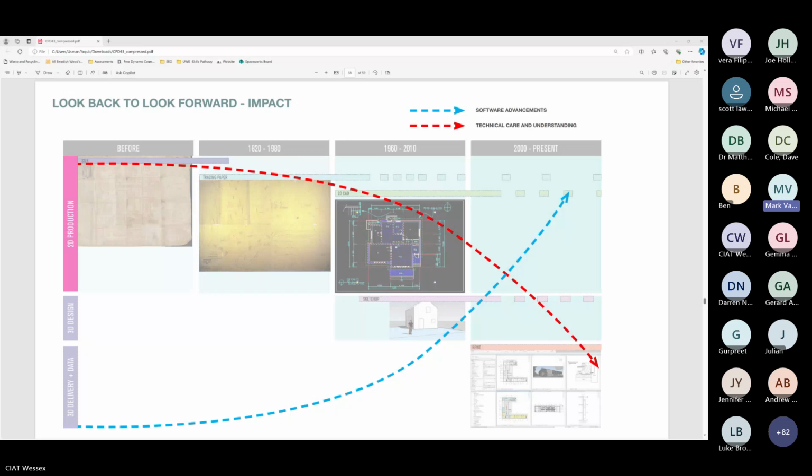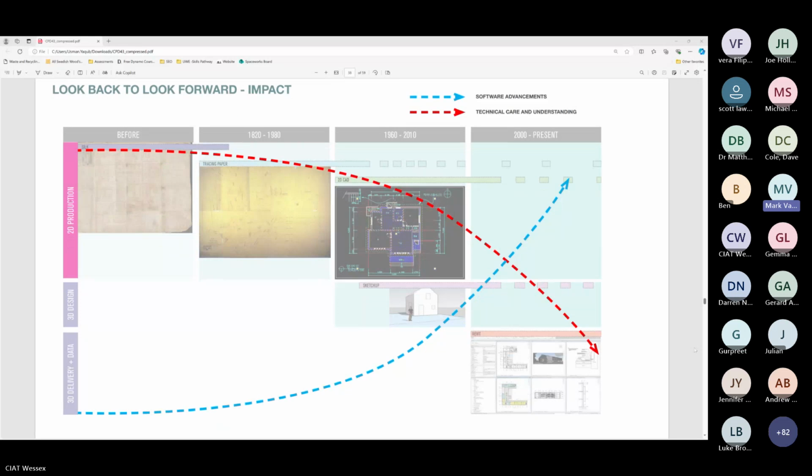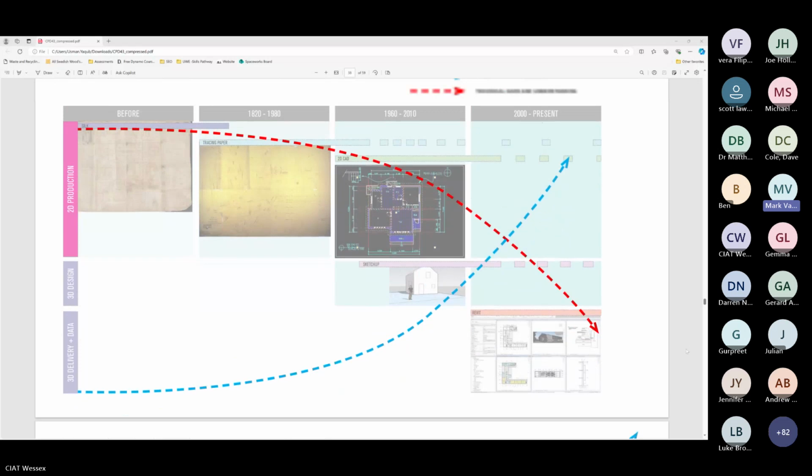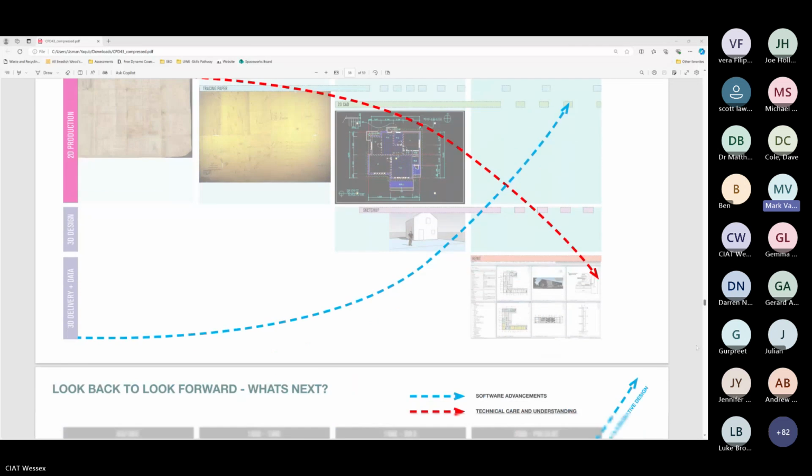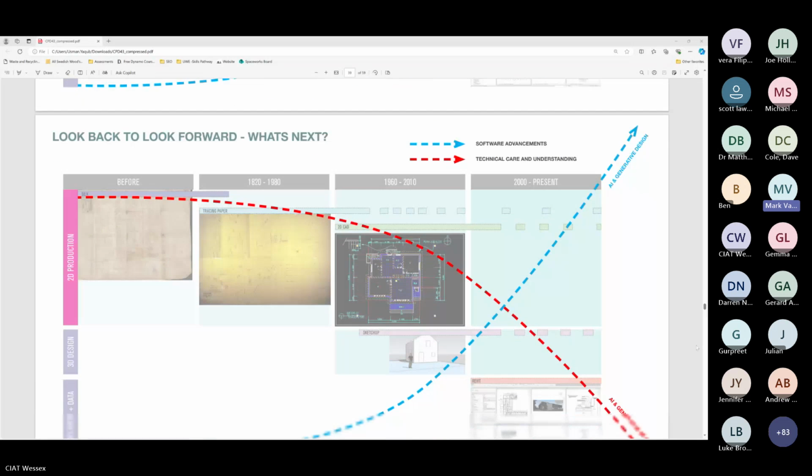But now that we move into Revit, you draw a wall in a plan and it gives you the elevation. You move a window in an elevation and it updates in a plan. And then you also just generate your sections. Generally what we see is the sections are the worst things that come out of it, because people focus on the plan and the elevations, but they don't think about the sections as much, certainly not the quality that comes out.